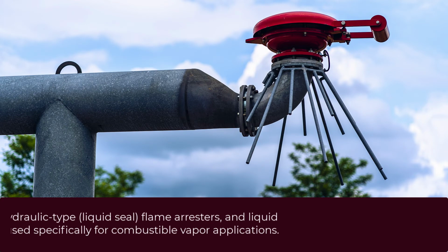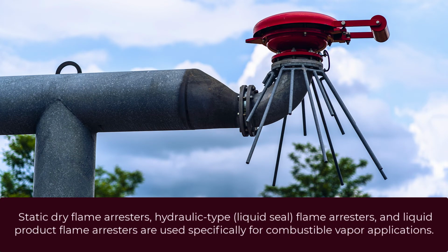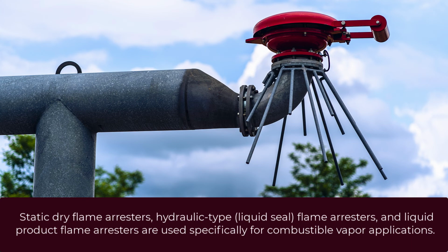The last three passive isolation devices, static dry flame arresters, hydraulic type liquid seal flame arresters, and liquid product flame arresters, are used specifically for combustible vapor applications and are not suitable for combustible dust explosion propagation threats. NFPA 69 provides descriptive requirements for the use and limitations of these devices.